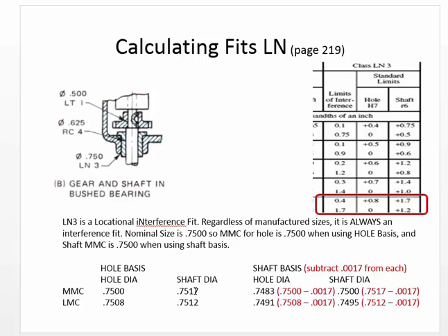What would it take to get that from what we had calculated? You've got to subtract 1 and 7 tenths, thousandths of an inch from each one. So once you've done that to one, you have to do exactly the same thing to the others. It's always subtracting. And when you're done, shaft bigger than the hole, shaft bigger than the hole. Differences 0.4, and the difference is 1.7.